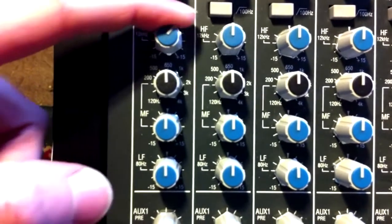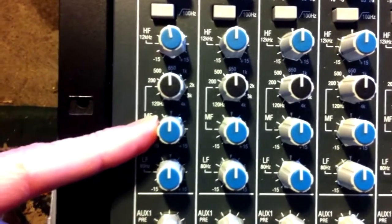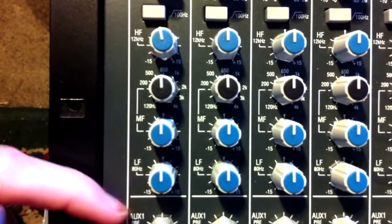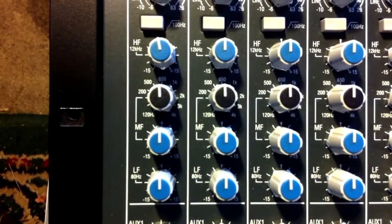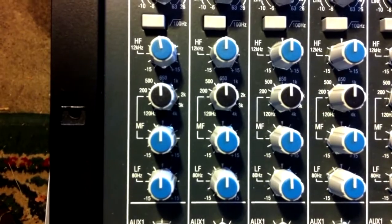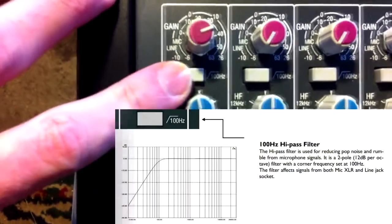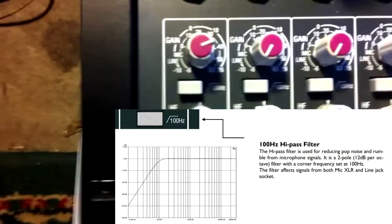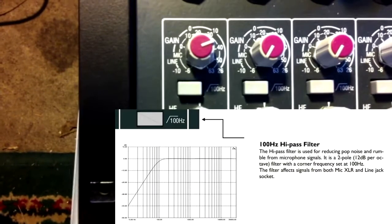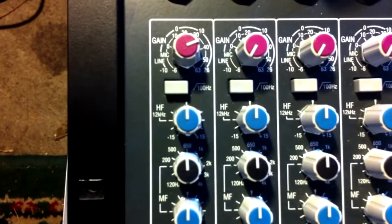So in this section we'll usually see high frequency or a treble, mid frequency, and low frequency or bass. These will give you control over shaping your sound. Do you want a lot of high pitches or a lot of low pitches? And over the EQ section you'll see a filter. This filter uses 100 Hz as its reference frequency. You usually use this as an onstage pop filter, so it'll take out the harsh sounds of your P's or D's or any other percussive sounds that somebody's mouth can make.